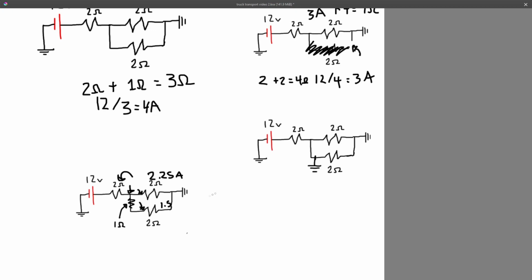Okay, I just cleaned it up a little bit so we can work with this circuit and not have to deal with a mess. What we have here, we have a short to ground right before our resistor in a parallel circuit, but because it's before on the parallel circuit, it cancels out this circuit, but it would also cancel out this circuit because current flows to the path of least resistance. The best path it'll take is this way.